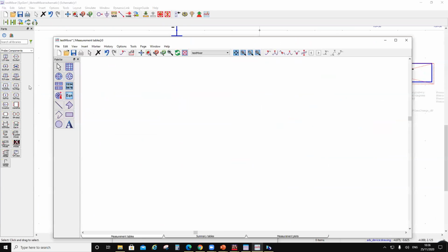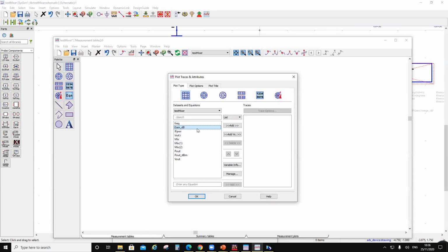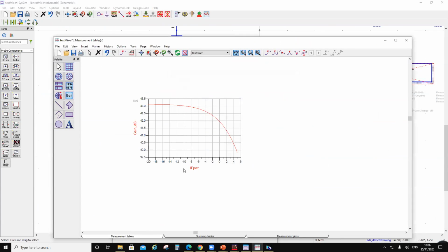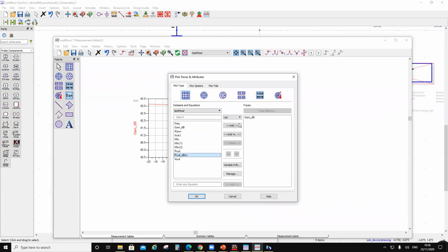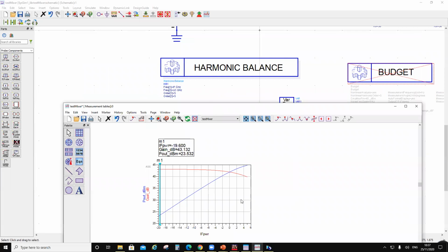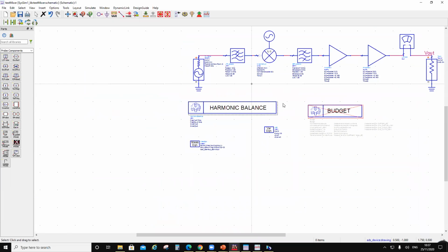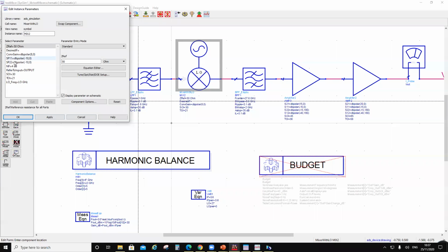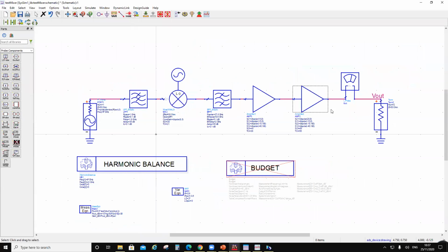Okay, so we are over here. We were doing gain compression. Okay, so the gain was doing like this. Okay, so let's see at -3.6 where we were. Let's put out a P out dBm, and let's put here the gain. Okay, so now you can see what happened. That's why I repeated it. The reason I repeated it was here, I was not putting dB polar, I was putting polar. So it was regarding this as a positive number. So that was why we had absurd numbers here.